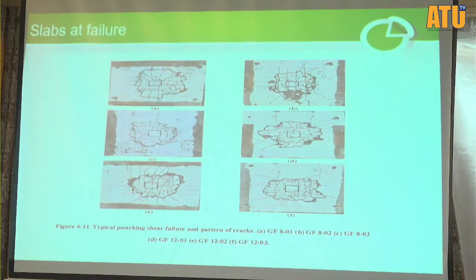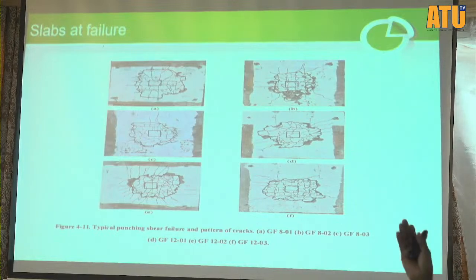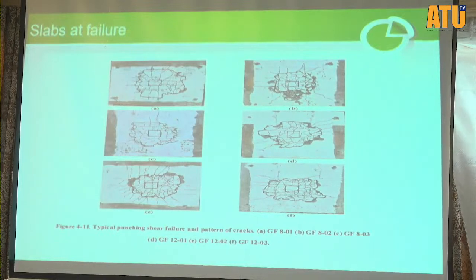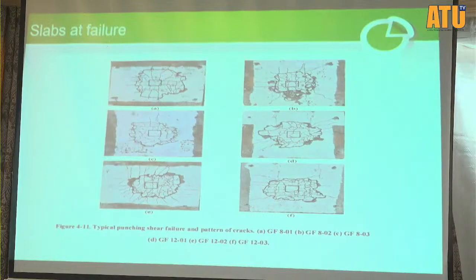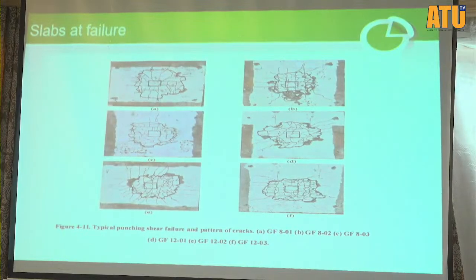If it is a flat slab, what we can do is have other drop heads, right? We can use a drop head to increase this thing. But if it's a point load like we are doing, enlarging the base will not work much. So either we bring in steel in that way, assuming it's a point load, a heavy machinery load at the center, and we want to prevent punching.